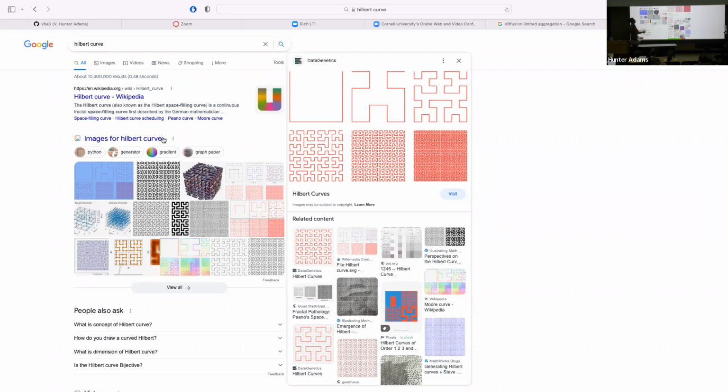We had a group that did this 2 years ago, sort of a proof of concept thing, where the pictures that they generated were very simple ones. It was just 8 pixels by 8 pixels, and each pixel was either black or white. Right? So that's 8 by 8, that's still 64 pixels, which means they generated 64 direct digital synthesis synthesizers, each of which would synthesize a different frequency. And then they would traverse those 64 pixels by following the Hilbert curve. If a particular pixel was on, then that synthesizer would turn on, and they would synthesize the frequency associated with that pixel. If it was off, then they wouldn't.